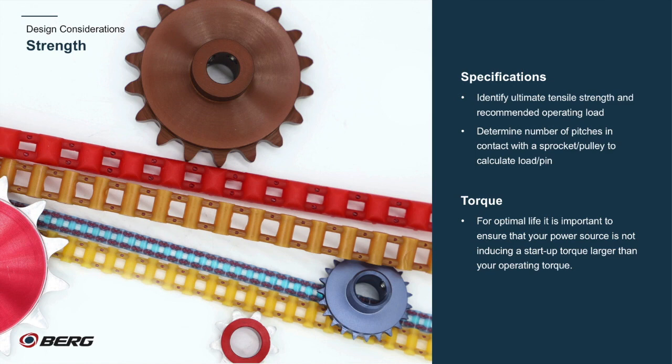If the force from the system exceeds the strength of the belt, either larger diameter sprockets could be used, if there is room, or a different system will need to be chosen. If the target belt force is known, the sprocket size can be calculated directly using the input torque to the drive. It is important to do these calculations prior to the design effort. It will be more difficult to fit a drive system into an existing design than to design around an appropriately selected system.